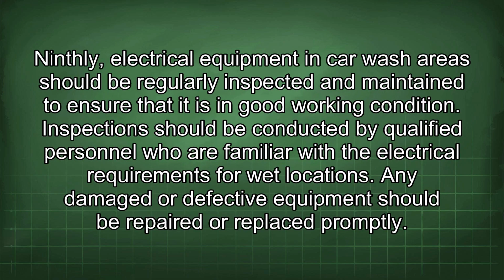Ninthly, electrical equipment in car wash areas should be regularly inspected and maintained to ensure that it is in good working condition. Inspections should be conducted by qualified personnel who are familiar with the electrical requirements for wet locations. Any damaged or defective equipment should be repaired or replaced promptly.